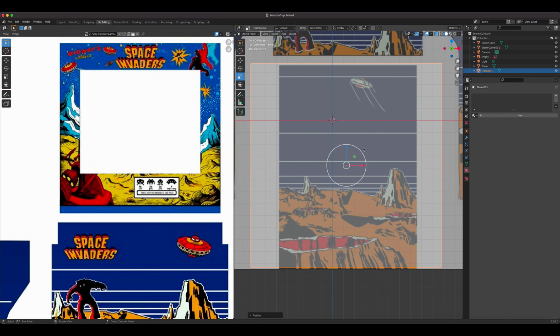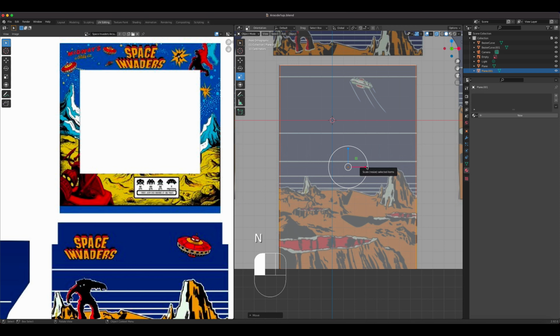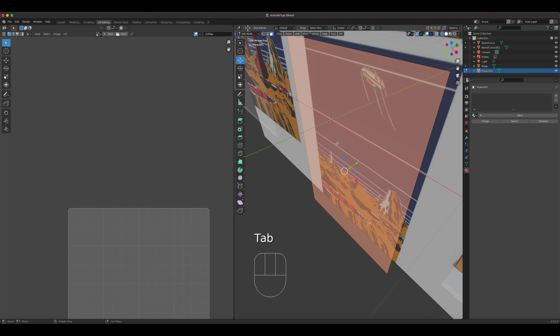And I'm in the UV, so I'm just working here, and you can definitely go to the modeling tab if you need a little bit more space. And let me turn on my screencast. All right, right there's good. Okay, and then what we need is simply to extrude this a bit. Just press E, give it thickness right there.